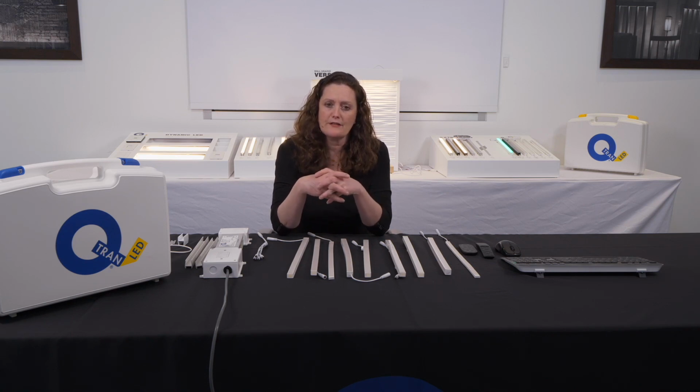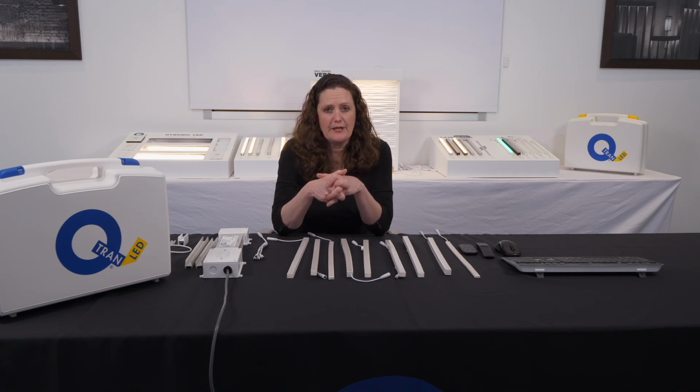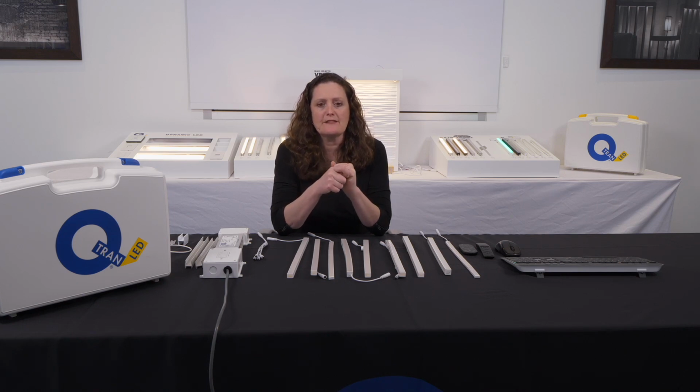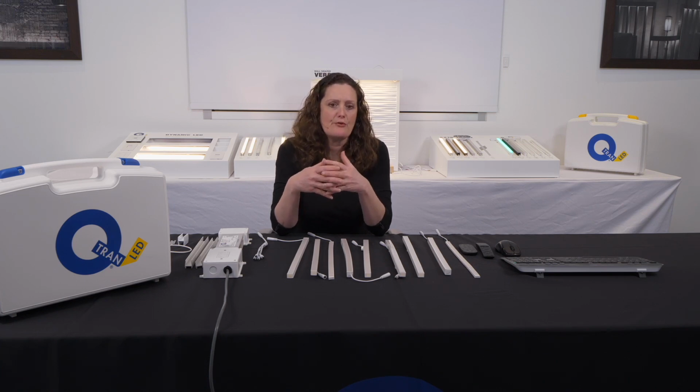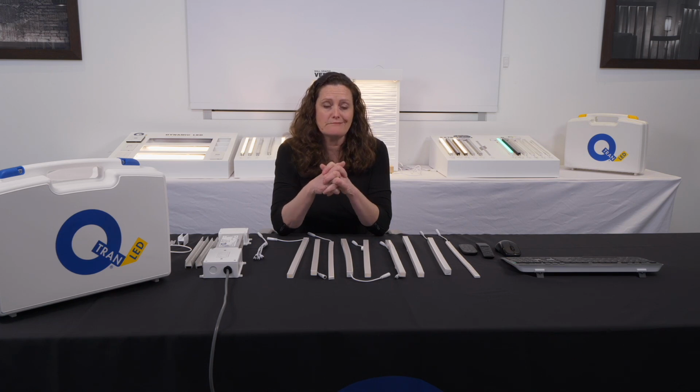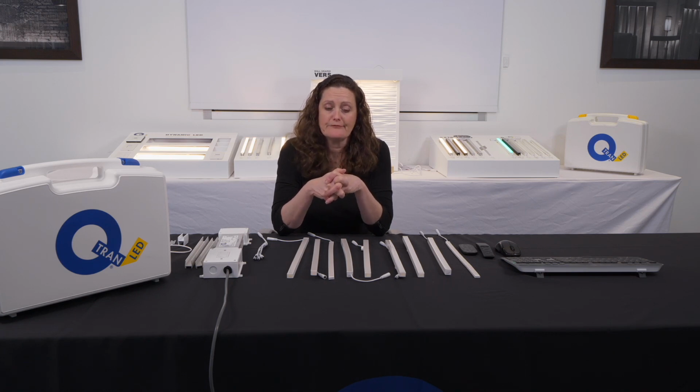So you might want a 20-foot fixture and do pass-through wiring, and you might very well be within class 2 limitations of 96 watts or less, but we might tell you there could be some voltage drop or lumen loss. So you might be better served by having two 10-foot fixtures rather than a max fixture and a 4-foot fixture. So all that nuance we're going to help you figure out and help you build these part numbers and build the fixtures that are correct for your project and fulfill the needs of what your priorities are.